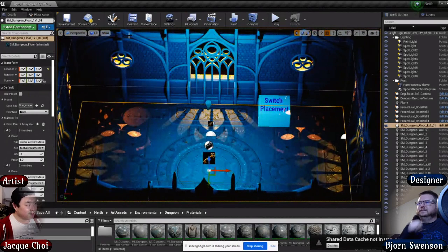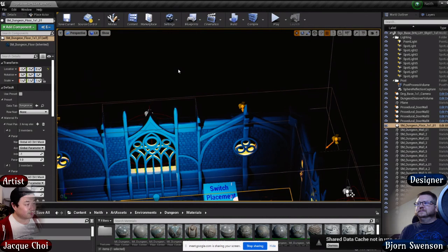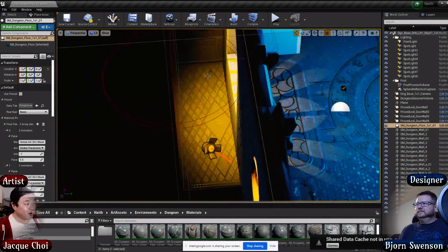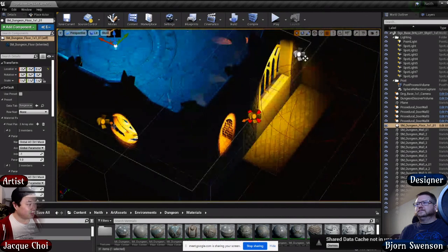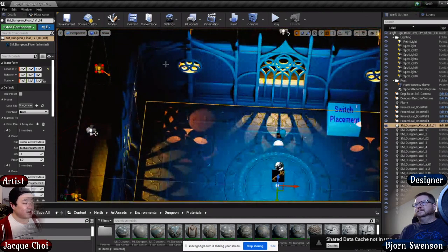I wanted to add some volumetric lighting in here, but the problem is I think it's very costly. So I'm looking at cheaper fake solutions, and one is adding collisionless geometry in there. There are different ways to do it, but it would be nice to get the rays coming through here. We'll play around with that. I also probably have to add a glowing polygon to the back of the geometry so you don't see the black through, and so we can blast that area here.